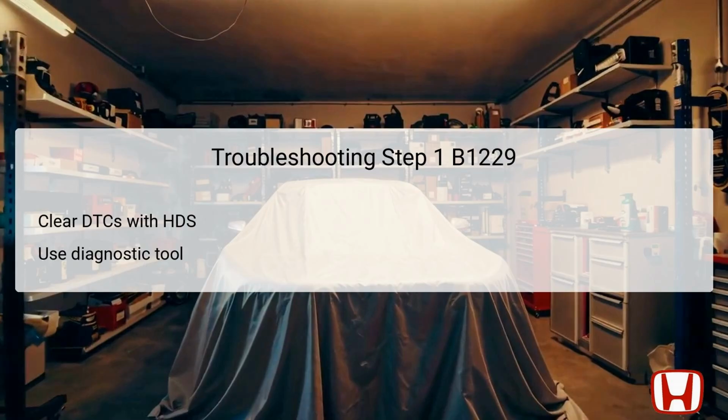If the DTC reappears immediately after the reset, it confirms that there is indeed a malfunction within the sunlight sensor circuit. Utilizing the HDS efficiently ensures that technicians can gather necessary data and take appropriate action based on the results.